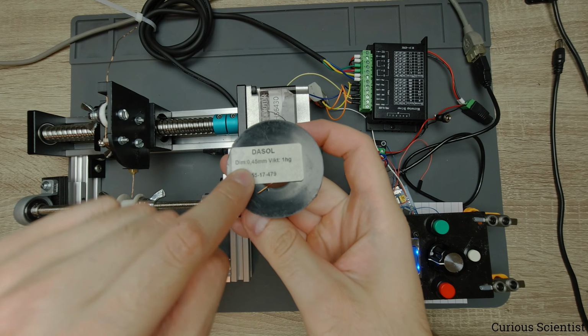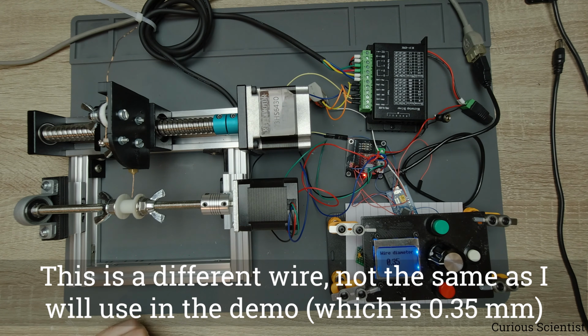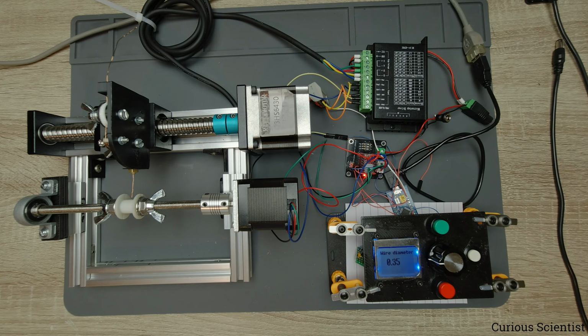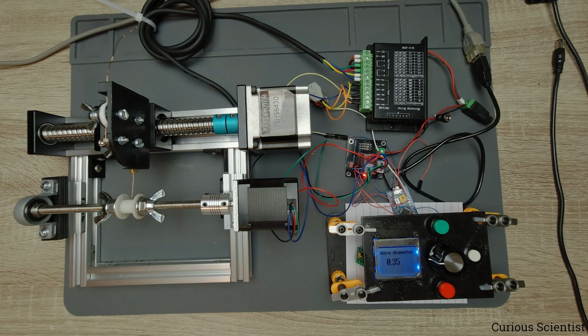So now the dimension is there, and it says 0.45 millimeters, but sometimes that's not true because sometimes they refer to the copper core's diameter and not the whole wire's diameter, because these wires obviously are coated and the coating is not counted. So sometimes this can be 0.47 or 48, depends. So you feed the real diameter here, and that will be important because of the displacement of the feeder.